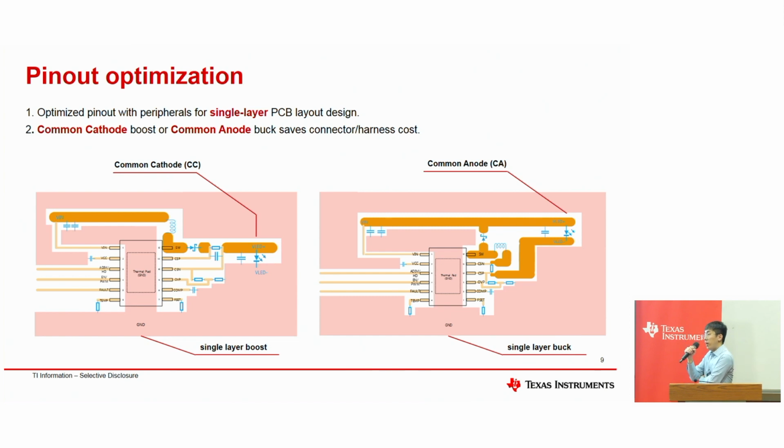Before we go into the LED dimming requirements, I also want to share some information from when we were designing this new chip from the start. When designing this new chip, we considered pinout optimizations to make it compatible with a single layer chip on board LED board design. Usually when the output power density goes up to 50 or 100 volts, the LED board can be really hot, and we have to consider using some exterior mechanical structure to dissipate the heat generated on the LED boards.